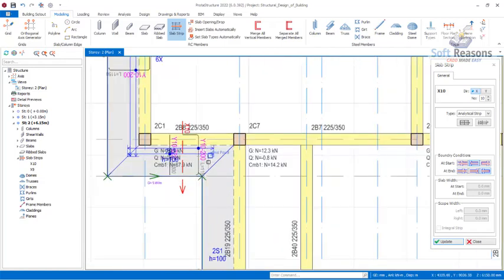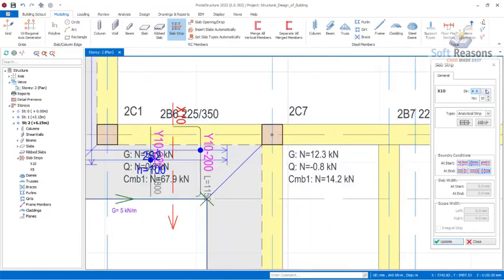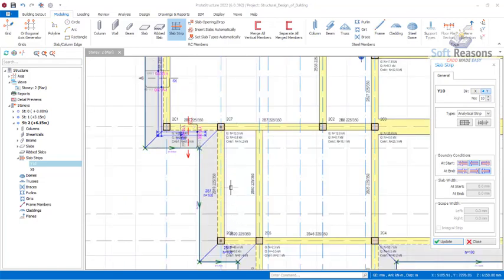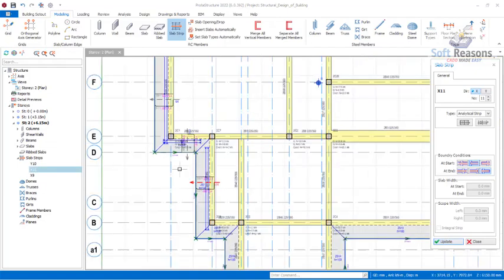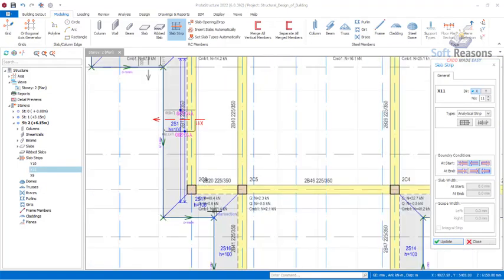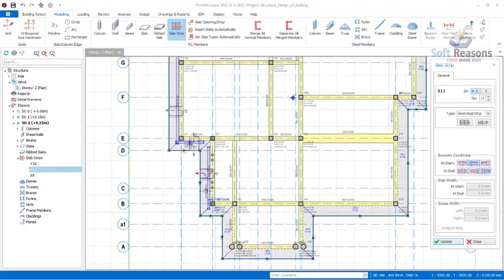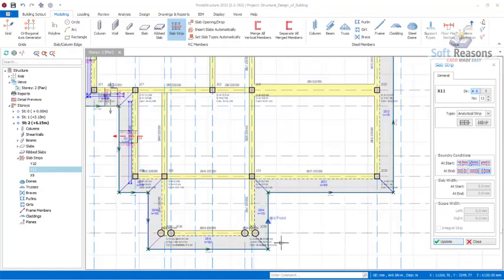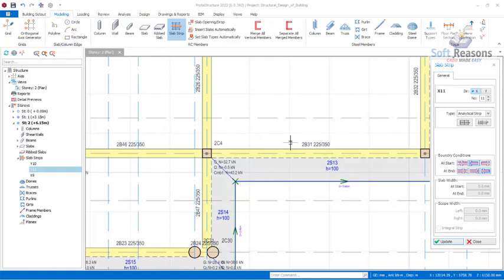So this is supposed to be the Y, like the vertical. So you select Y and click on update right there. So this has changed to Y. The next one is supposed to be X. So you have to have that. Select X, update. So this is basically for your parapet. Alright, so you can continue to place this all around, or you can use these rebar selections for all of the parapet design successfully. So let's add one here in the Y direction.